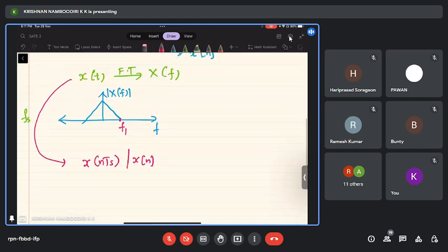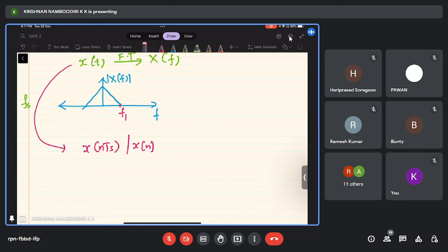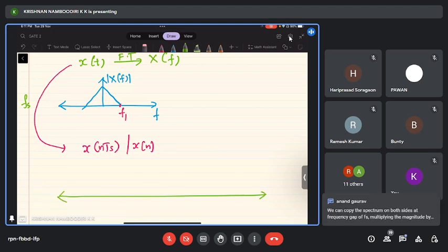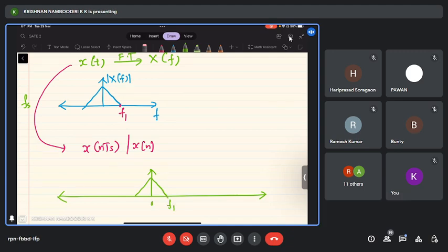I will straight away come to the point. I'm not going into any mathematical details. So the spectrum of the sampled signal will look as follows. This will stay there as such from 0 to f1, the maximum frequency component of the signal. And the same shape will be repeated, centered at fs, the sampling frequency, again at 2fs, again at minus fs, again at minus 2fs. So this is 0. These are the center frequencies.